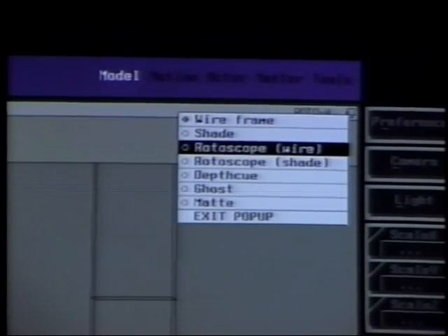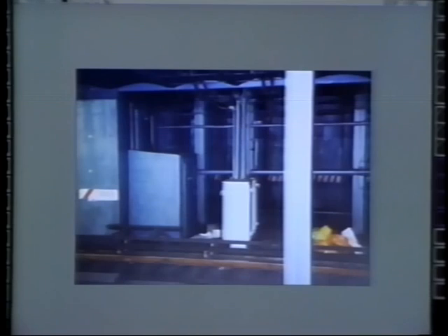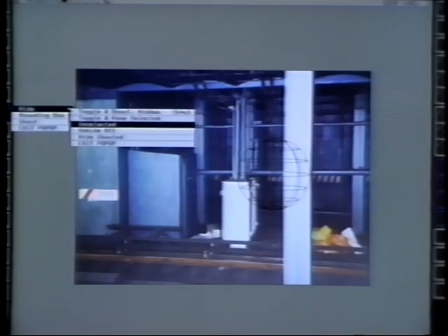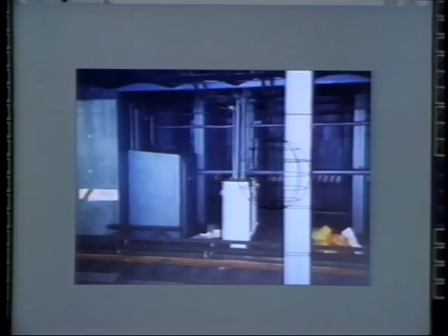Sometimes we need to make elements that will be partially obscured by a live action element or appear to be behind part of a separately rendered element. This animated sphere will be moving through this live action shot, which I've lined up as a rotoscope wire background picture. But this column in the shot should appear in the foreground, so I've made a simple 3D model to hold the place of the column.